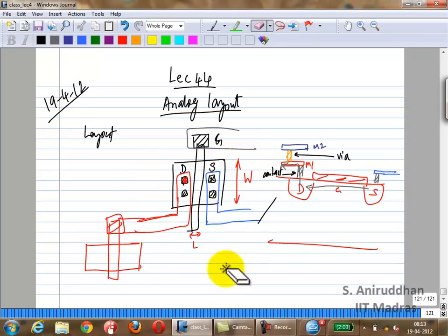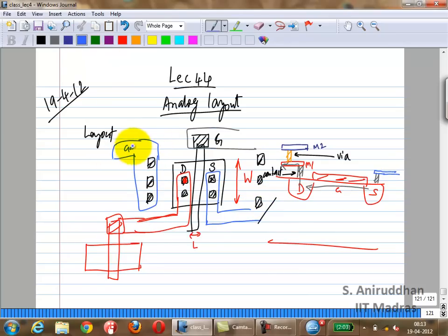So normally what you would do is put in substrate contacts separately for this transistor alone, and then you would probably connect it on metal. In this case, let's say it's connected to ground. Because you are not going to rely on the very resistive connection. The global connection of the substrate could be happening elsewhere. So you are going to put in contacts connected using metal layers to ground, to make sure these transistors have a good ground connection. Is that clear to everyone?